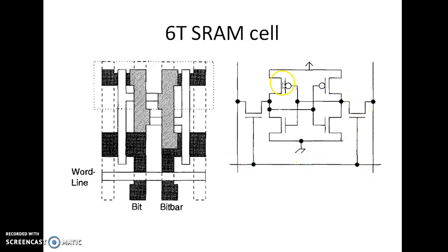Only the resistance is replaced with a PMOSFET. And the word line and bit line produce complemented outputs, and it would be in read or write state if the word line is given logic 1. And it would be in hold state when this line is given logic 0.